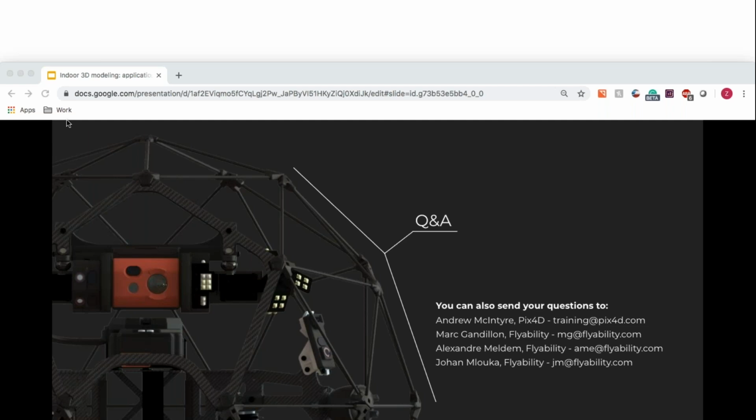Okay, I hope I understand the question. I believe they're wondering whether it's possible to take a reconstruction that was reconstructed in relative space, and then georeference it, align it, co-register it with a completely separate reconstruction that is georeferenced in absolute space, so we can actually get a sense of where we are on the planet. And the answer in a single word to that question is yes. The longer answer is you need more information, right?